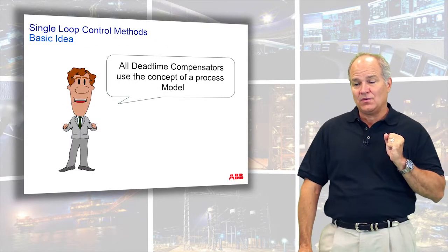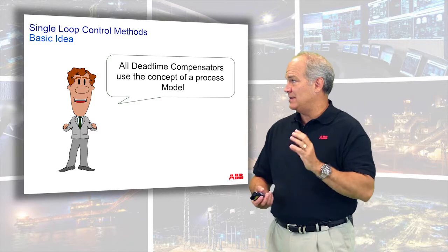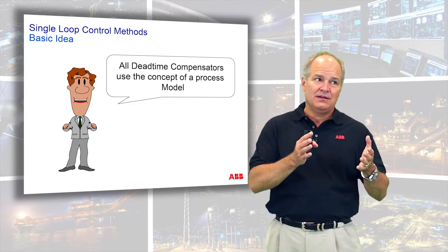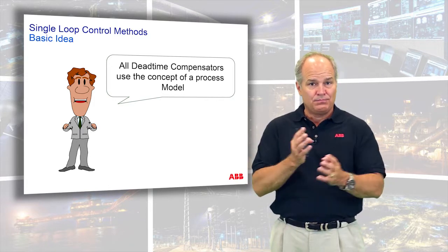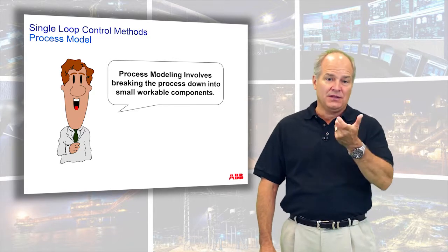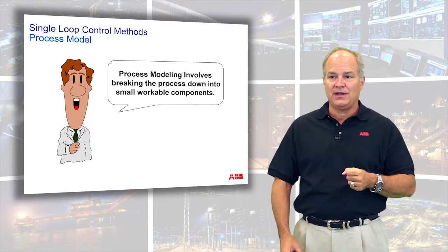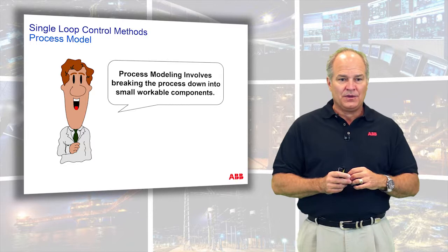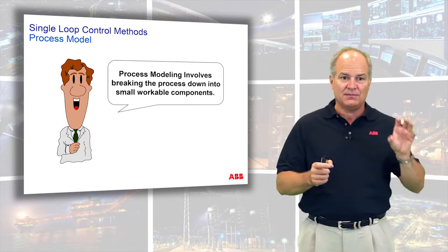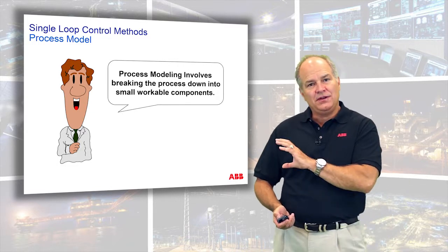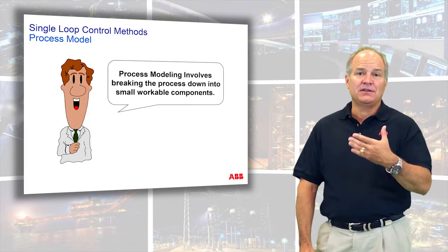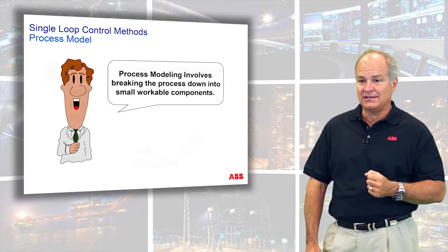So the idea here is, first, we have to calculate the process. We have to figure out a model and then break it up into its parts. The idea of process modeling needs to be looked at a little bit more in depth. We have to break it up into its pieces. We have to be able to think in terms of dead time, time constant, process gain, and actually think of them as processes. So what we're going to do here is step through a simulation and compare it to the actual process. And I think that will make sense.